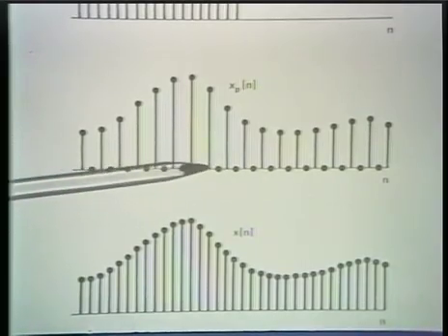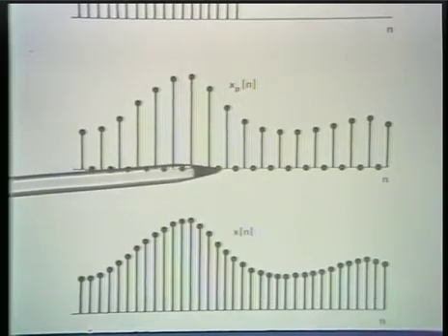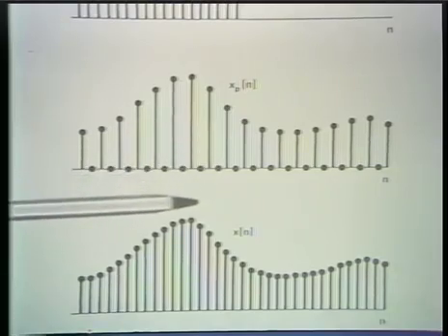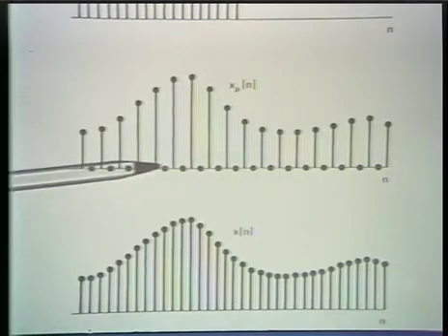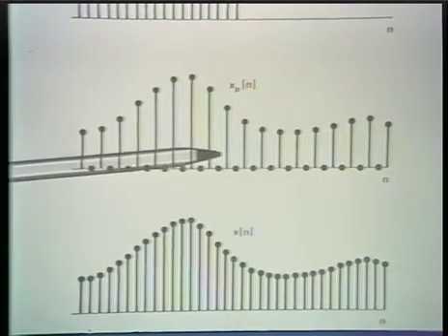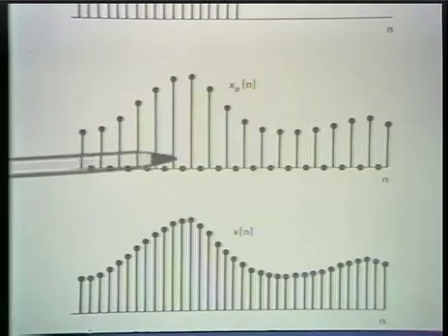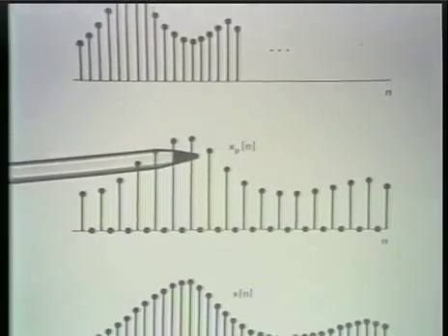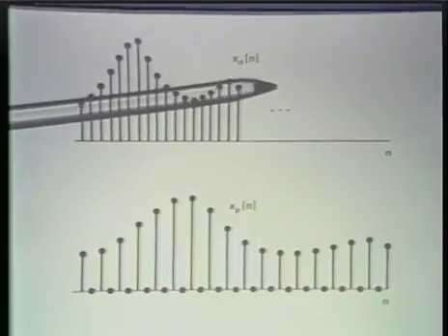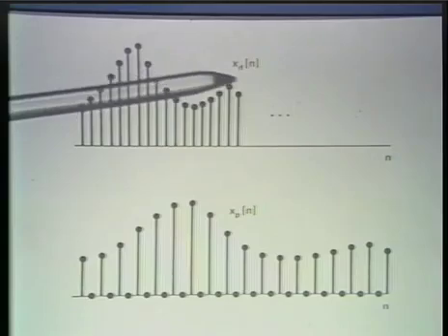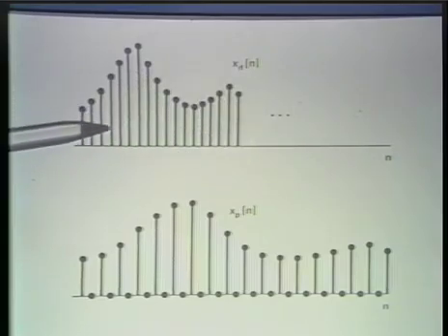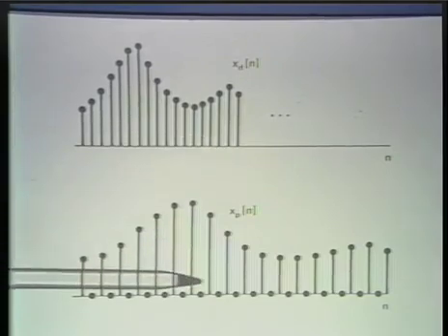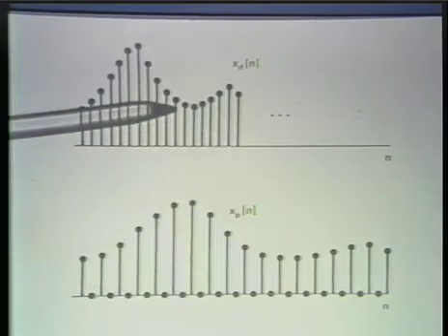Here what we're assuming is that the sampling period is 2, and so every other value here is equal to 0. The decimated sequence then is this sequence collapsed, as I show in the sequence above, and so it's in effect time compressing the sampled sequence so that we throw out the sequence values which were equal to 0 in the sampled sequence.